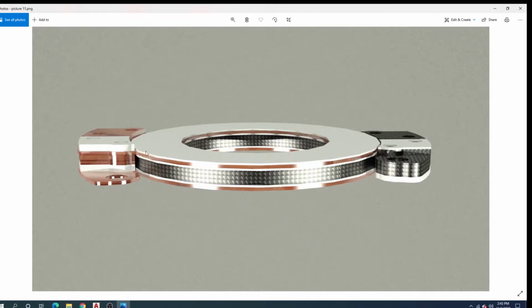Okay, so as the electricity is flowing through these individual layers, they're conducting a current, which means they're generating a magnetic field. And since it's a coil, all of the layers have the electricity traveling in the same direction, so those fields will add, or you have a summation of fields.